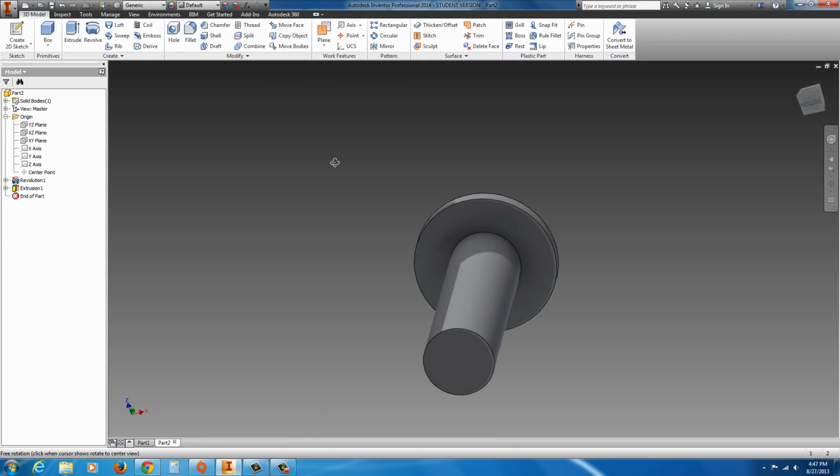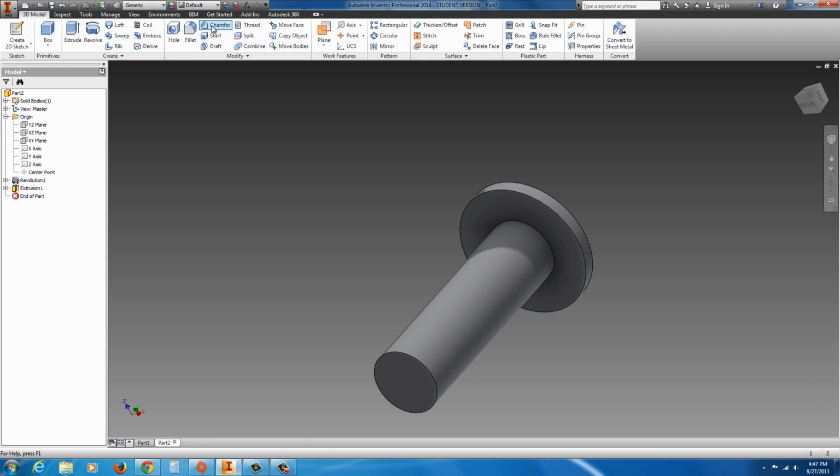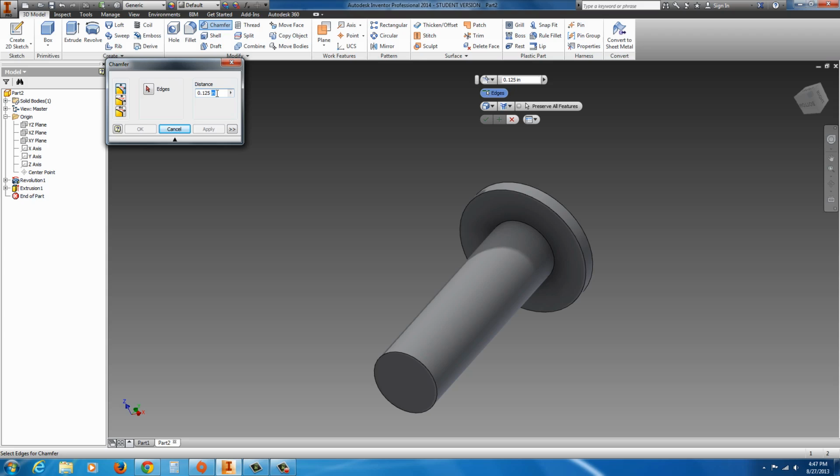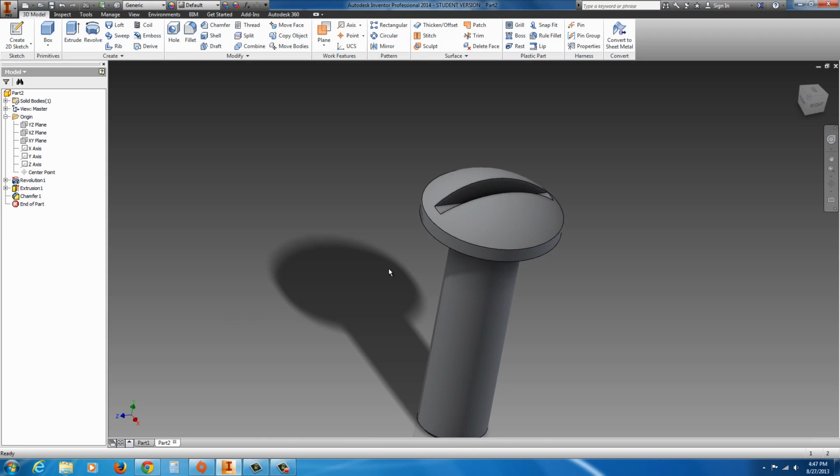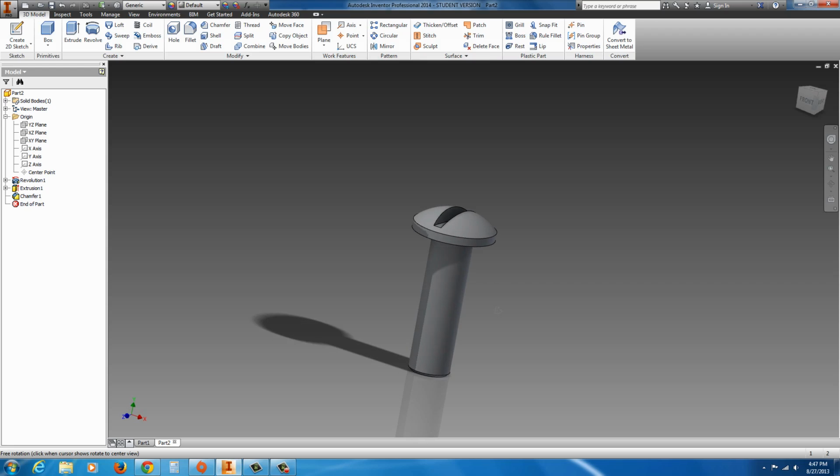Hit OK. Now put the chamfer on. Go to the chamfer tool, set it to 0.03. It should default to 45 degrees. 0.03. Select this edge, hit the green check. And that concludes creating the bolt. The thread is covered in the advanced class of exercise 13. Thank you.